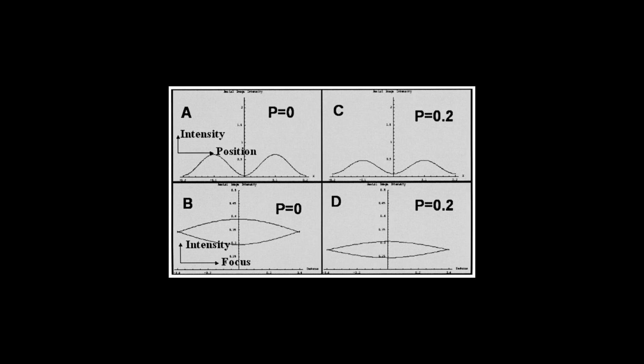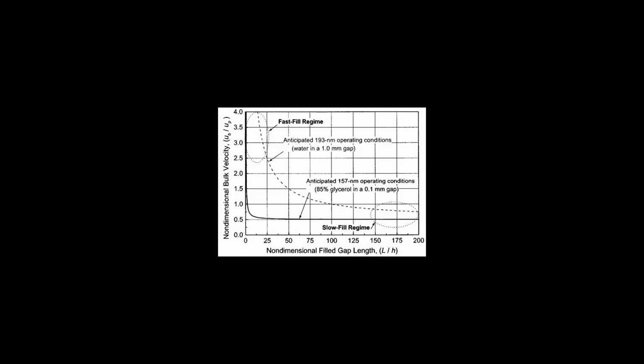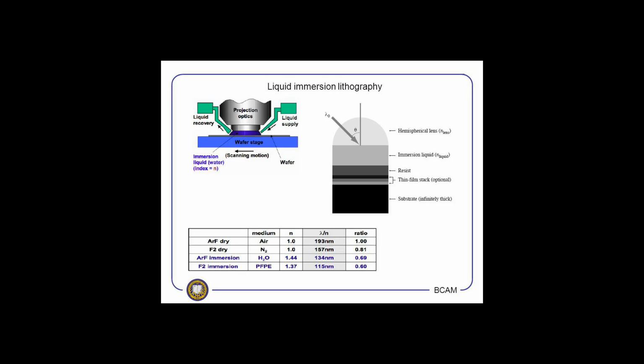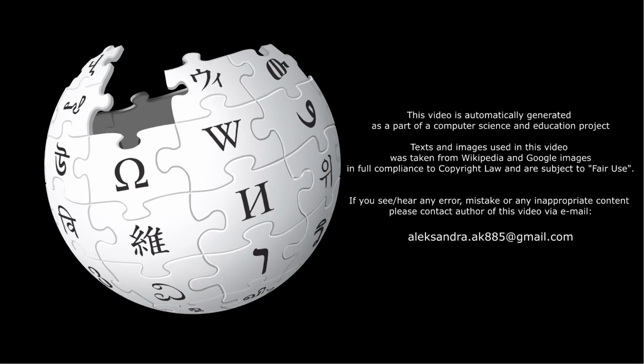Manufacturing issues. The main obstacle to adoption of immersion lithography systems has been defects and other possible sources of yield loss. Early studies focused on the elimination of bubbles in the immersion fluid, temperature and pressure variations in the immersion fluid, and immersion fluid absorption by the photoresist. Degassing the fluid, carefully constraining the fluid thermodynamics and carefully treating the top layer of photoresist have been key to the implementation of immersion lithography.